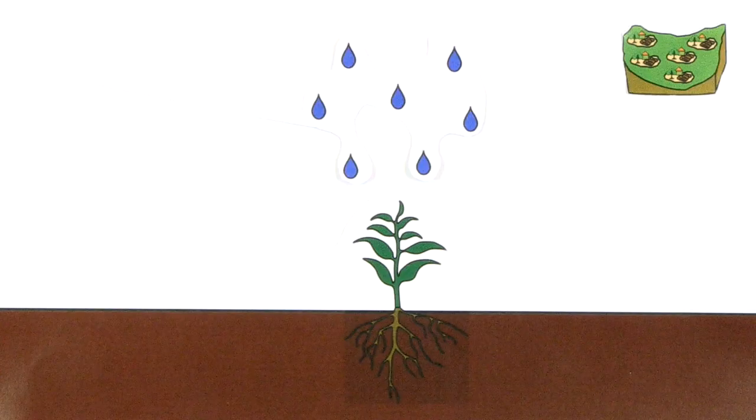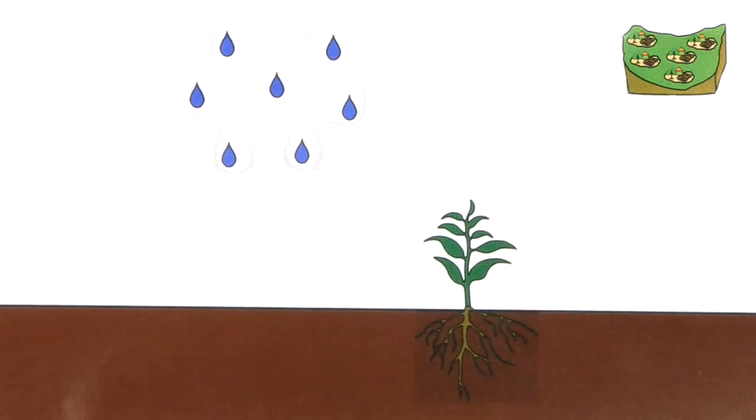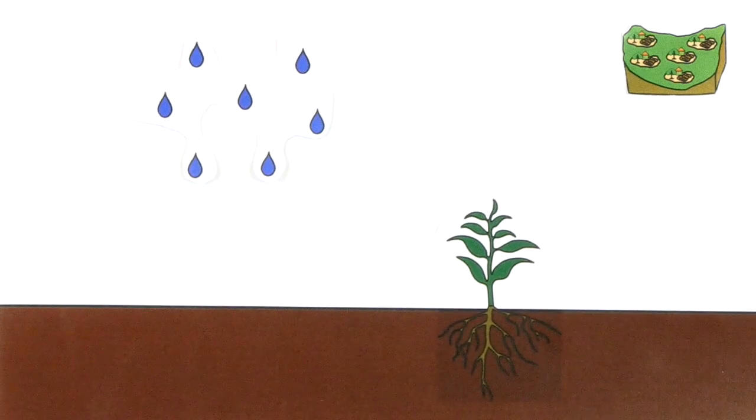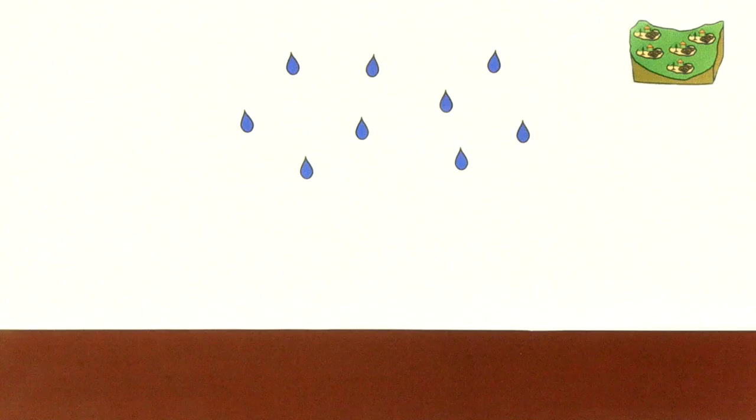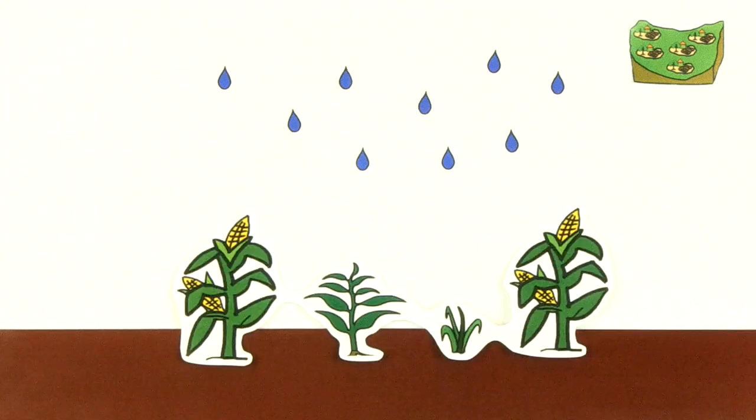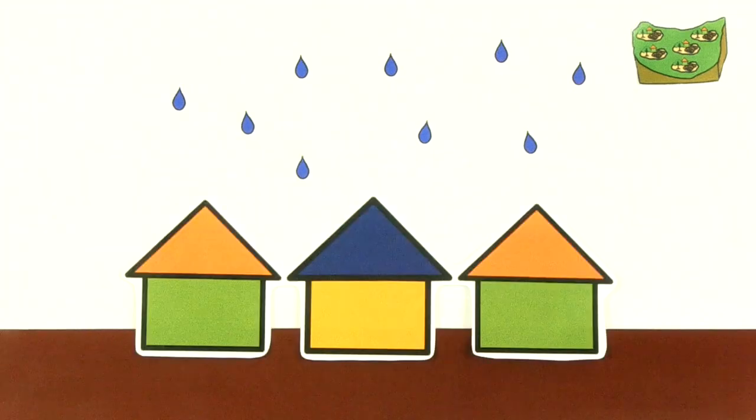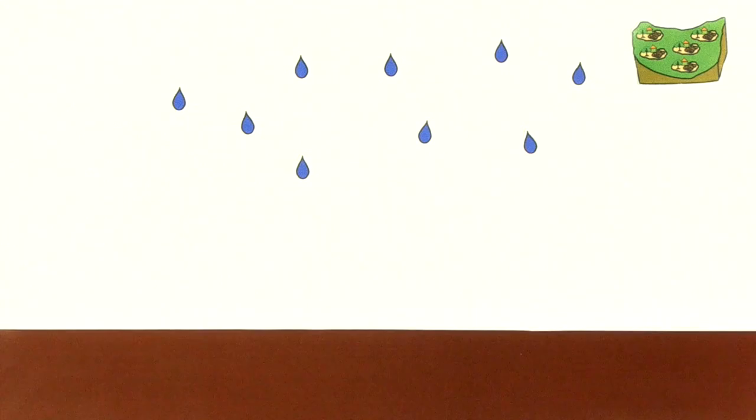In macro-catchment rainwater harvesting, the catchment area lies outside the application area. This means the rain is not collected where it is used. The land cover of the catchment area can be manifold, including cultivated land, roads, or settlements. Often, the catchment area is located on a hill or mountain slope.